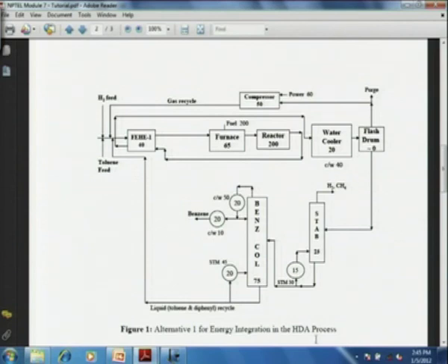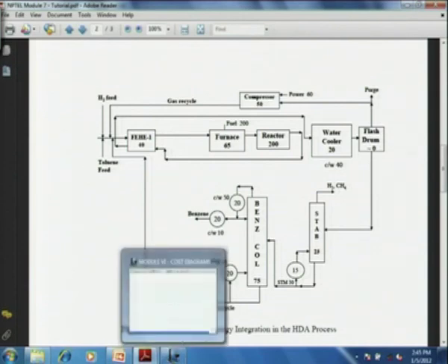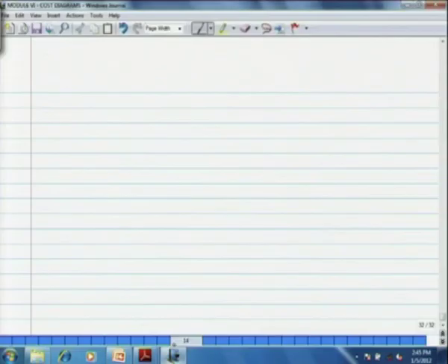Okay. Here we have only one feed to effluent heat exchanger, whose capital cost we have to distribute between the two streams that it is treating. The stream 1 is the reactor feed and the stream 2 is the reactor effluent. We are given the heat transfer coefficients as 0.69 kilowatt per meter square per Kelvin for reactor feed, and again 0.69 kilowatt per meter square per Kelvin for reactor effluent. Yes, so we have to distribute that cost, and since the coefficients are same, the cost will be distributed equally. Okay, that point we note.